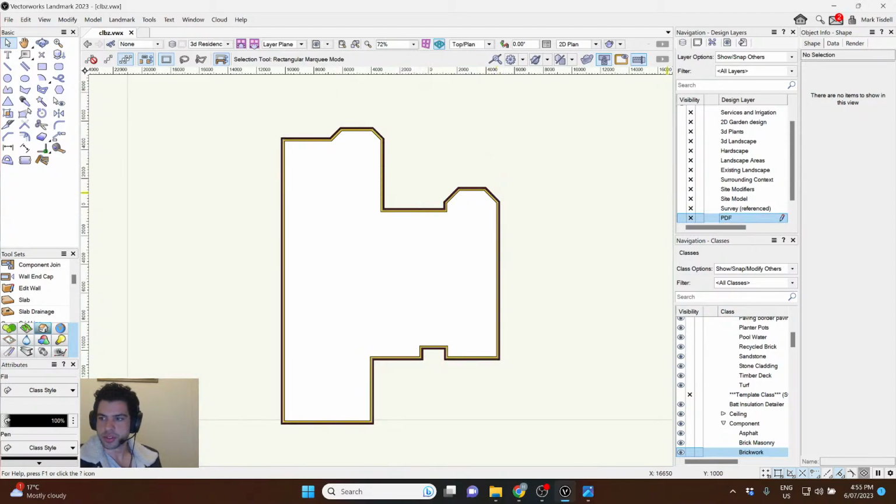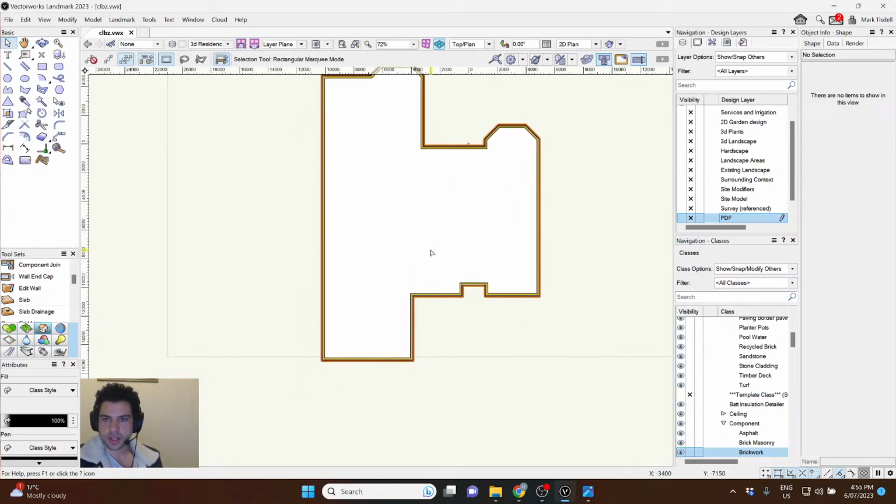Now, bit of a tricky spot here. I'll need to go through and put in the doors and windows without having a true sense of where they are. So you can go about doing that with the Windows and Doors tool that's in the Building Shell tool palette.